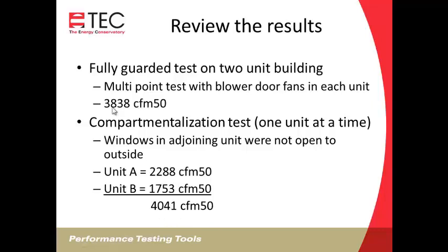So we can see the difference between our two numbers, our fully guarded test, our leakage to the outside for that entire building, if it were tested as one zone, is 3838, and we had a little more than 200 CFM higher. So we've got some leakage between the units.